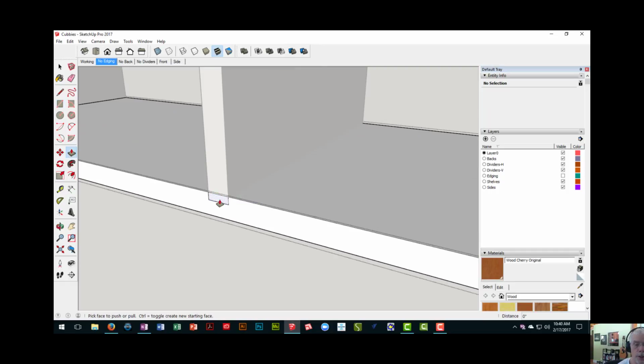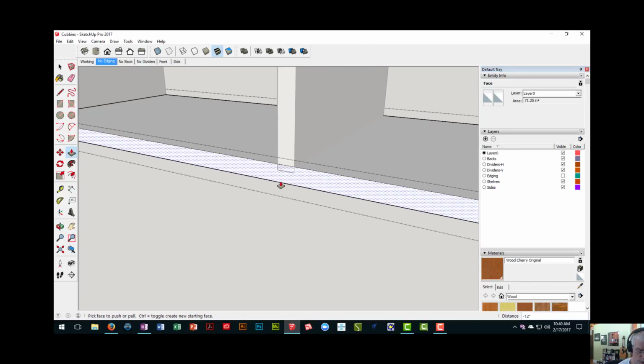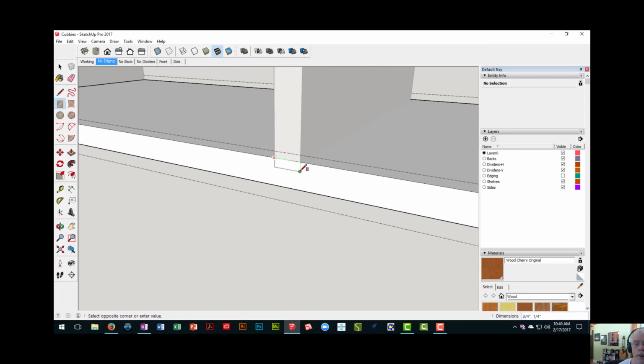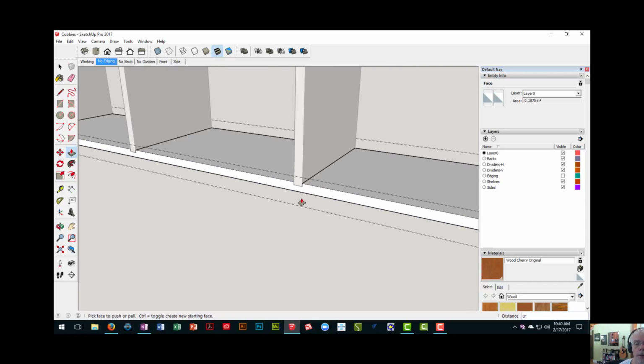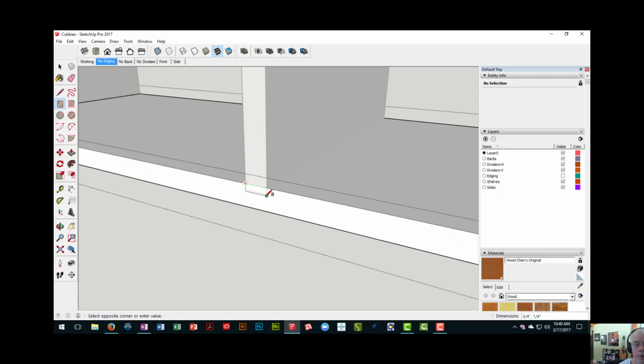And so I'm going to go back to push pull and manually push it back there. But now it should be in the right direction. So when I grab the rectangle tool and cut the next dado and press P for push pull and double click, it pushes it all the way back 12 inches.